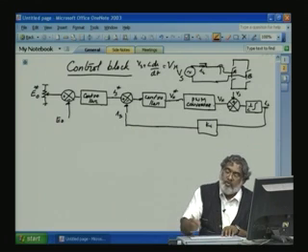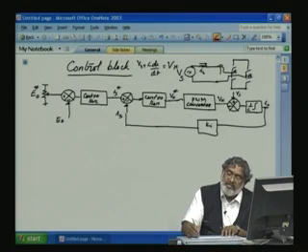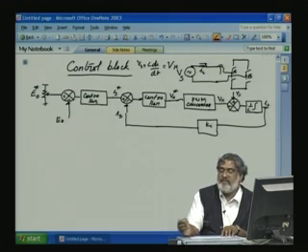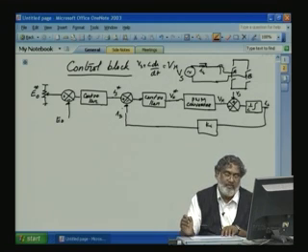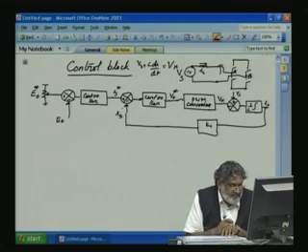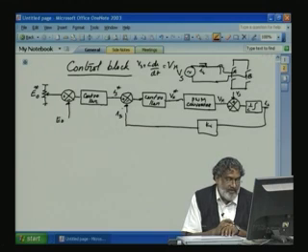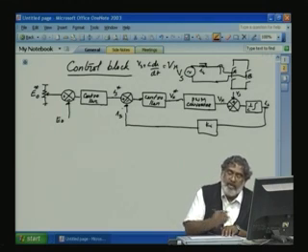Now, this is the converter output. Vs minus Vr, through the 1 by L integrator, will give the Is value. This Is you step down, and you can feed it back here. Now, Is we got.